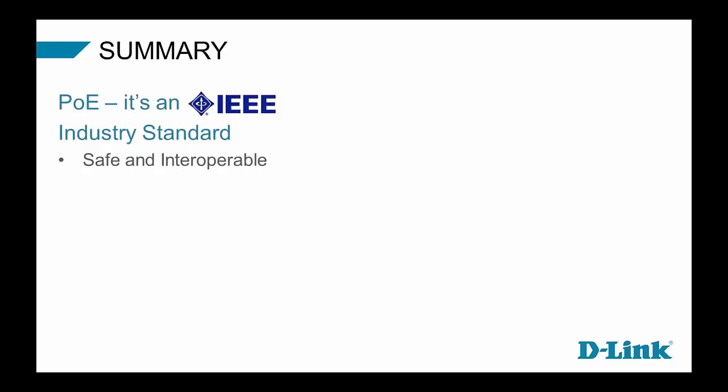Okay, so that's kind of a wrap-up of all things PoE, what we talked about today. To me, the most important, IEEE standards. We had the different standards, 802.3af, at, and the standard that was ratified last year, 802.3bt. Why do we need standards? Interoperability, of course. We want to make sure that vendor A's switch is interoperable with vendor B's access point or IP camera or IP phone, but it also ensures that we have safety built into the technology.